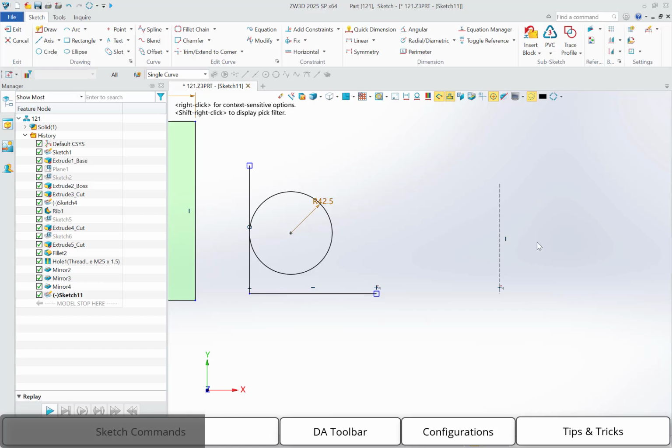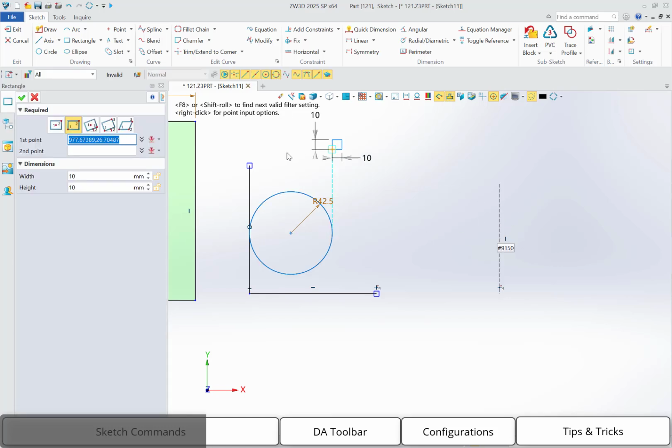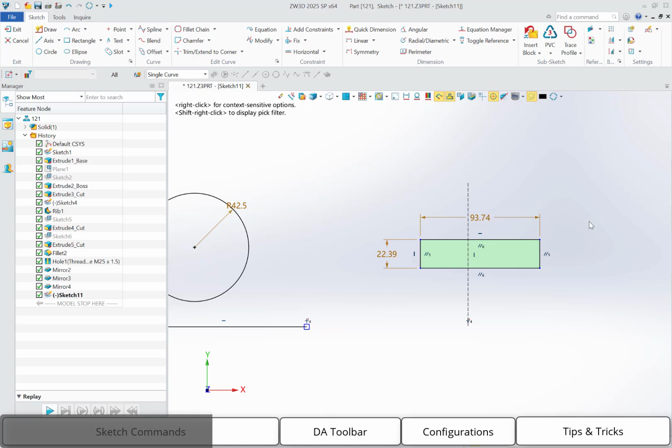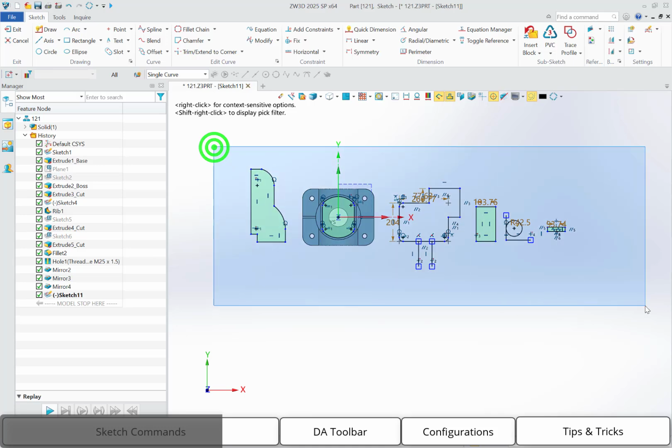And then we draw a rectangle. You can turn the rectangle into solid. Okay, here you can pay attention to how I do the constraints. I select one, one, two, three, then I select symmetric. Okay, that's basically all about the dimensions and the constraints. Now we will delete all the useless sketches.